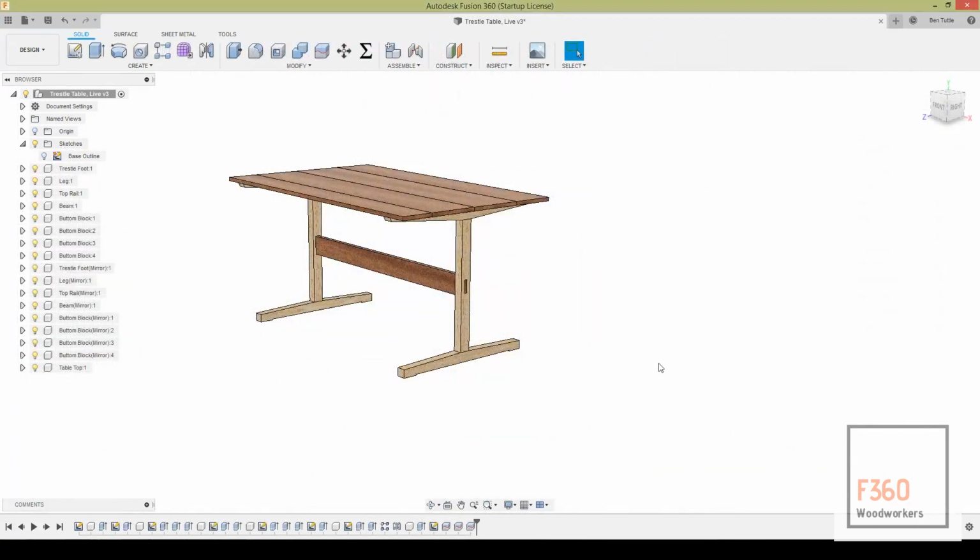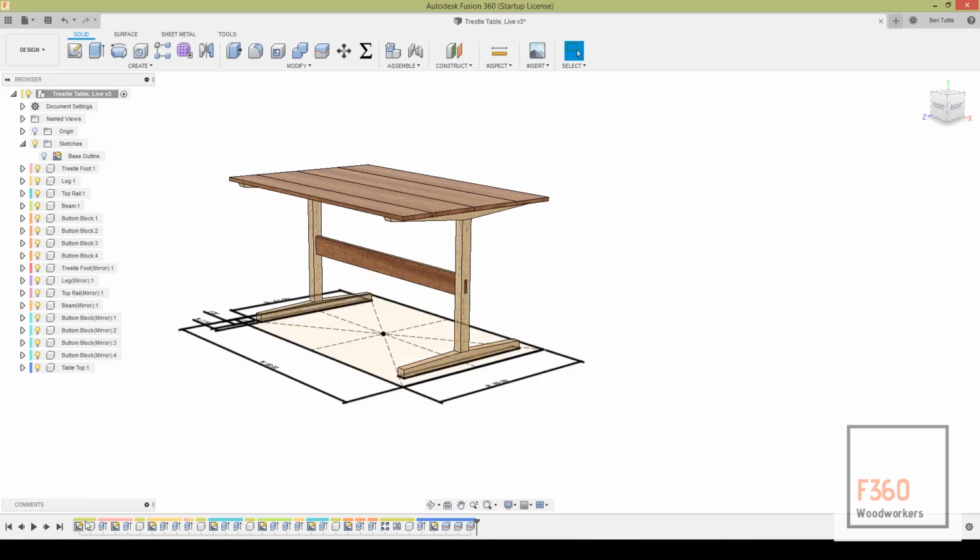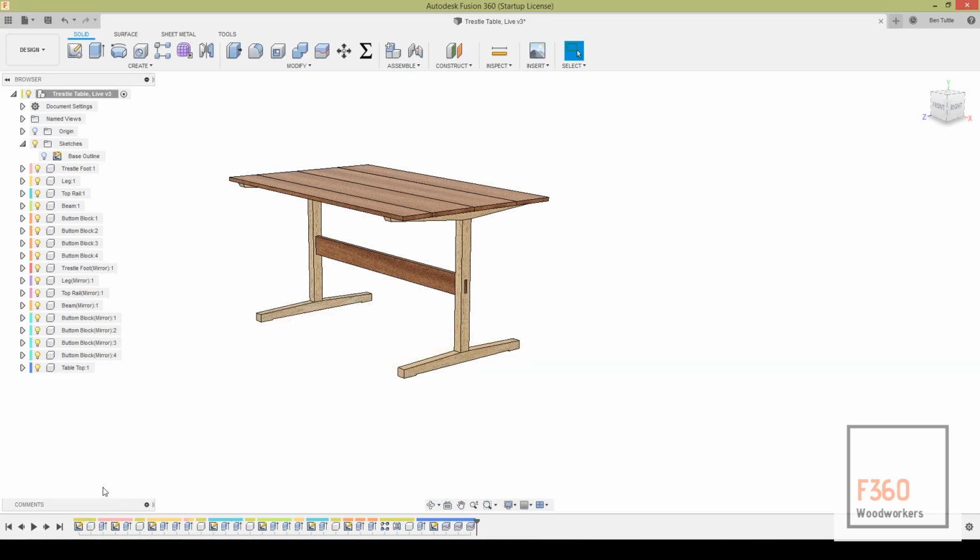Two more quick things that maybe a lot of people just beginning in Fusion would like, and that's the component color swatch. You access that by clicking this gear icon and checking component color swatch. What that does is it'll show you, for example, these first two features in my design timeline. That correlates it to something in my browser right here.